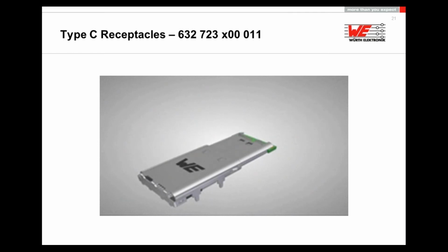And that is the reason why you have to choose the right connector for the right PCB you would like to use in your application. So, for example, there's a different part number if we are speaking about a 1mm PCB compared to a 1.6mm PCB. And that will also affect the routing and the PCB design because of the signal.